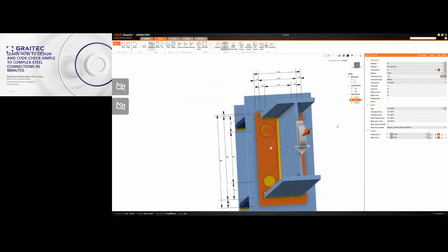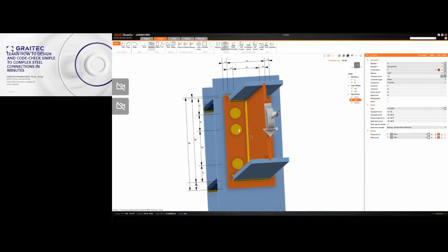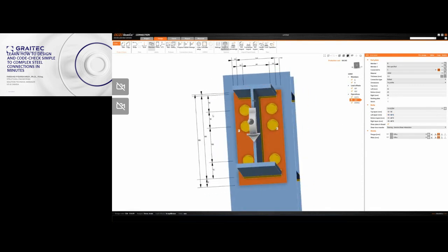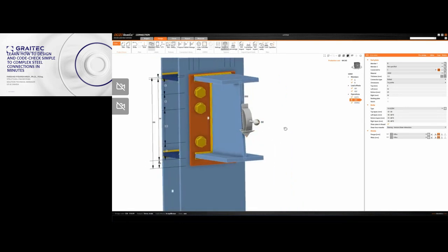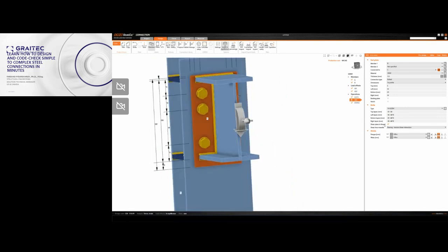And the other one is times 0, so it doesn't count. But let's say if I want another one, I can just type another minus 50 to add another row of bolts here, which is going to be a distance of 50 millimeters. So removing and adding bolts are also simple from here. You have control of all of those locations.